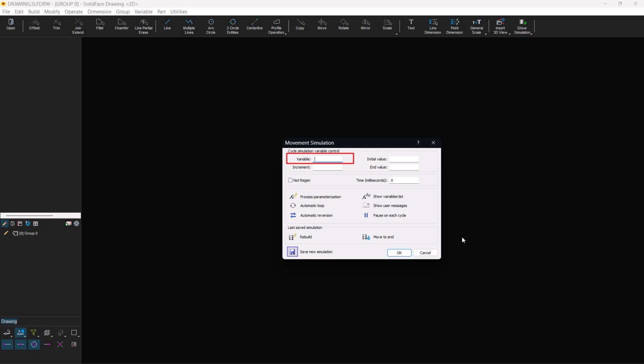In our example, we are going to show a connecting rod crank mechanism movement. The rotation angle variable used to rotate the mechanism's hand crank is also the control variable used to count the simulation cycles. When the simulation is complex, that is, with alternating movements, translation, and rotation, another variable is used to control when these steps should be set, normally by logical conditions. In this case, the control variable is only used to count the simulation cycles, for example, 0 to 1000, and the end of the simulation is normally carried out in a logical condition.